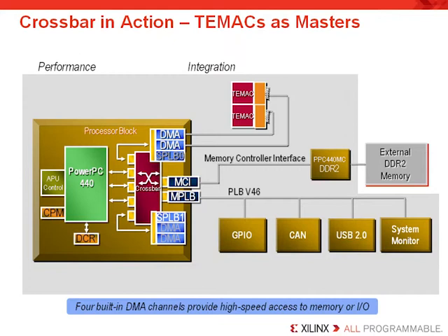Note that this TEMAC we're building here differs from the XPS_LL TEMAC component, which is attached to the PLB bus. The XPS TEMAC component supports the hard TEMAC included with Virtex 4 and Virtex 5 FPGAs. The XPS TEMAC also supports the soft implementation. That would be one that is not built with dedicated silicon, as it would best be in Virtex 5 or Virtex 4, but instead would be built targeting a different FPGA, using standard LUTs and registers of FPGA logic. And likewise, that TEMAC, since it's built with LUTs and registers, would be slower than the dedicated one in silicon.